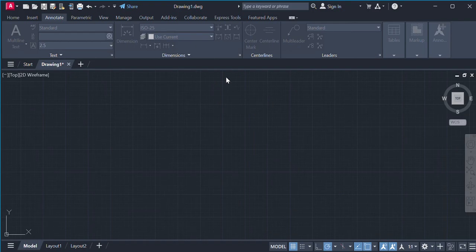So once you've clicked on the drop down arrow, then you can select new. This is because as it comes, it already has annotative or standard for you, but you want to create a new one that you can personalize, so that should you want to go back to the standard or the annotative, then you still have an option to choose them.